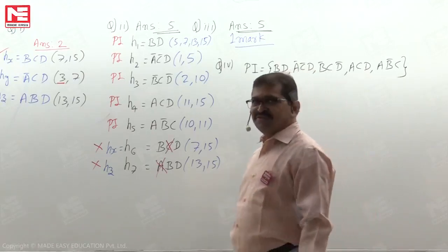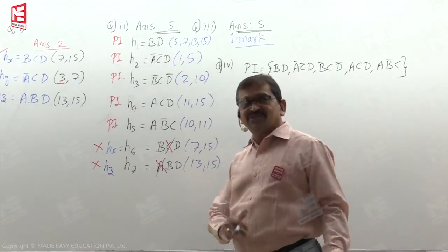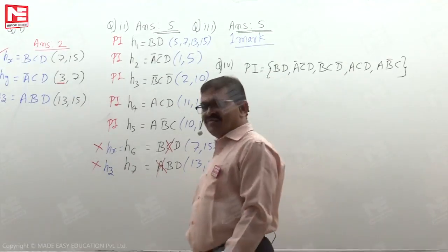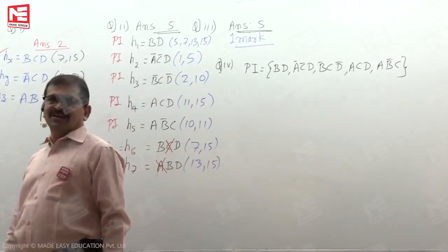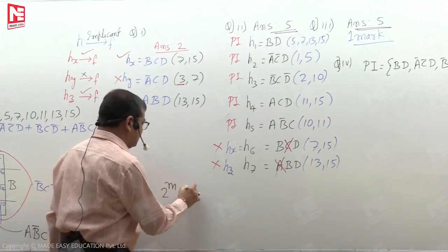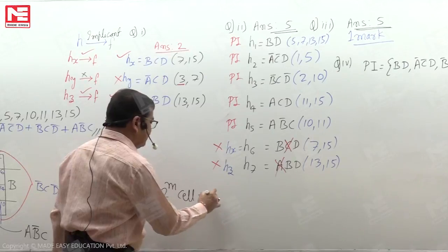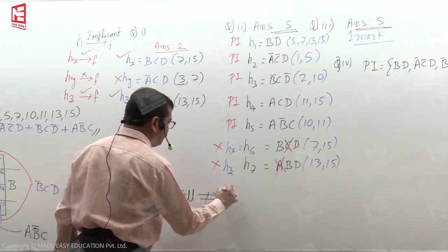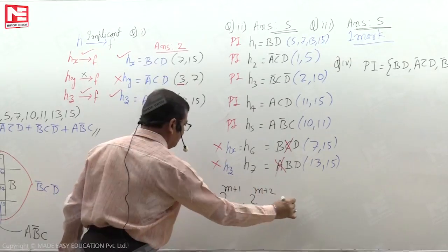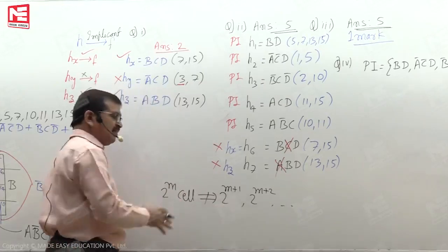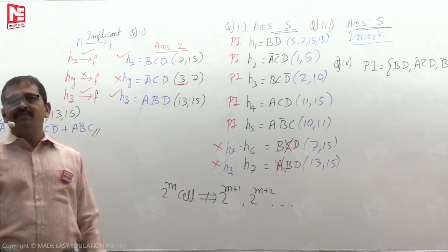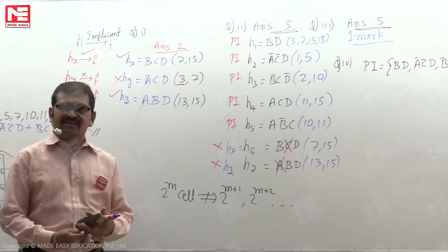Now I can explain the condition I mentioned in our earlier discussion on the basic part of the K-map. One condition I mentioned was that when you are marking a subcube of 2 to the power of m cells, we must take care that it should not be part of any larger size subcube. That was the statement we noted. Now, with all this work, we can understand why this condition is required while marking subcubes, and why we are not marking them randomly.